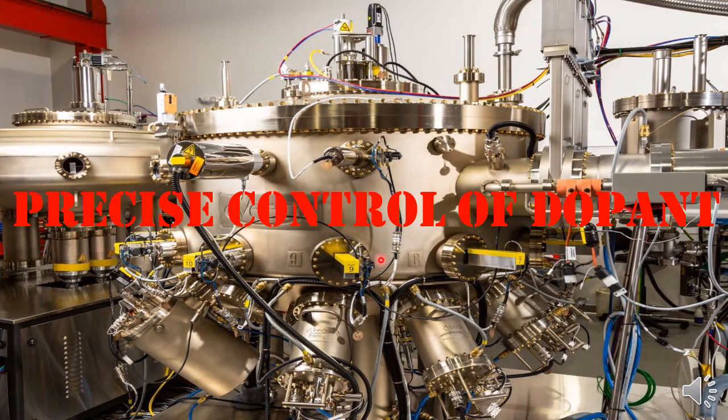The dopant is introduced in the form of pulses, controlled by an electronically controlled shutter, which is located at the top of the effusion cell in which the dopant is present. So this technique allows us to incorporate a precise and controlled dopant into the surface of the thin film or inside the thin film.